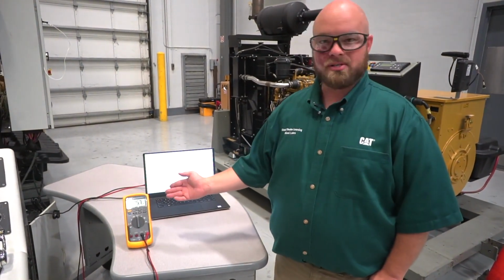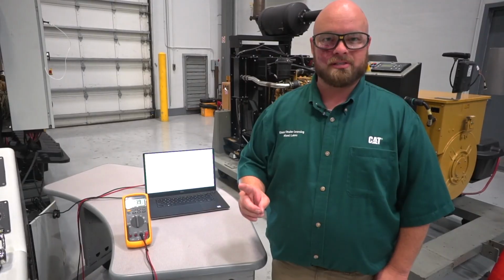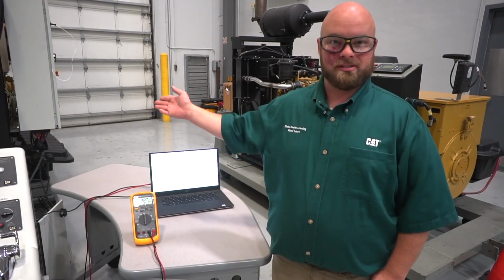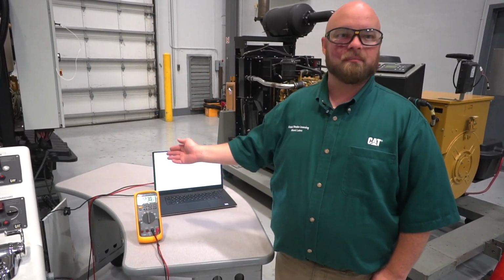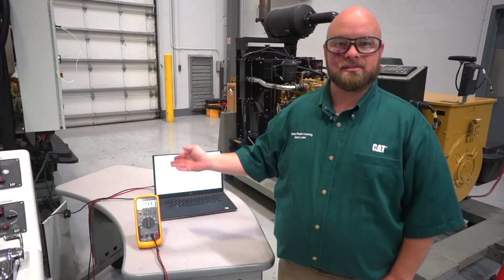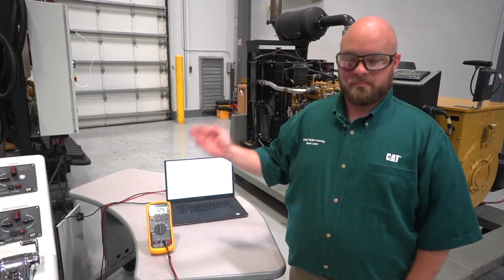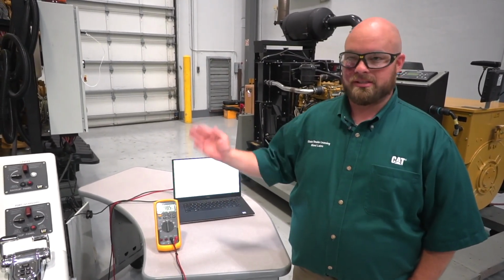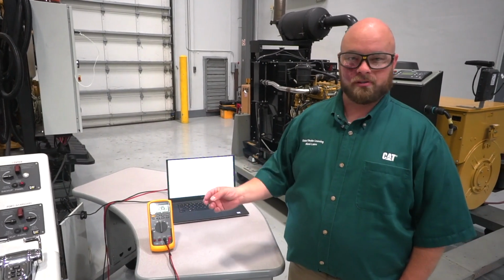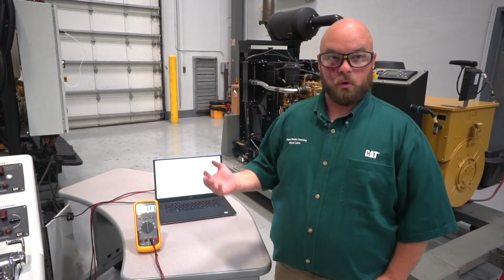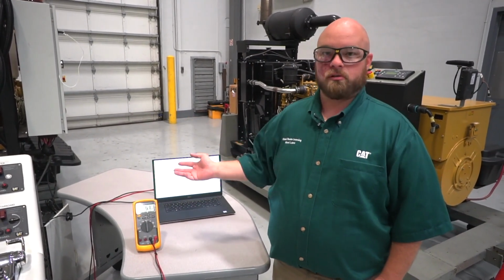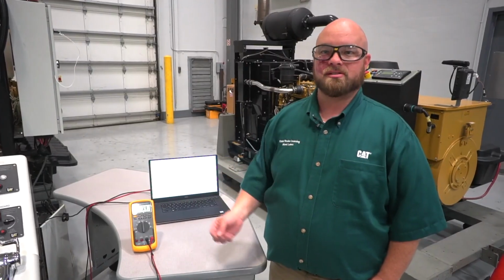Well, the way that we're measuring right now, we forgot one very important step. We still have the power to the system on. When you see crazy numbers like this or really high resistances on your CAN network, sometimes some people may think that there's an issue going on there, or that that's an open circuit condition. What it really means, and most likely, is that you've forgotten to turn the power off. So we always check resistance with the power off.